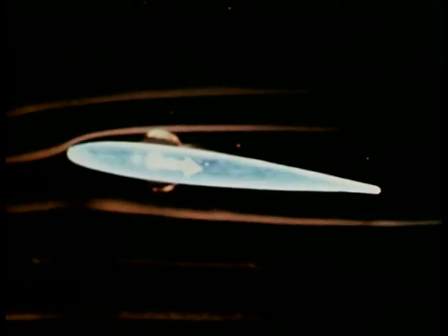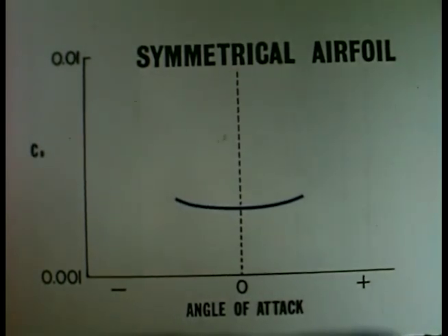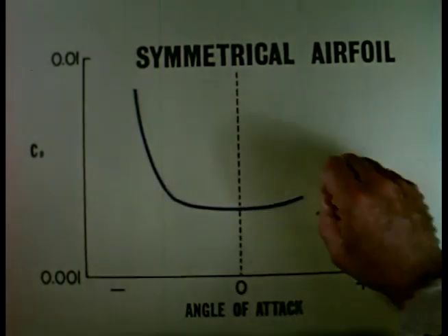Many practical problems, such as flows about airfoils or pump blades, involve both skin friction and form drag. Little or no separation occurs on a thin foil at small angle of attack, and the drag is largely attributable to skin friction. It is roughly the same as that of a plate at the same length Reynolds number. But separation sets in when the angle of attack increases, and form drag becomes predominant, increasing the drag coefficient considerably.